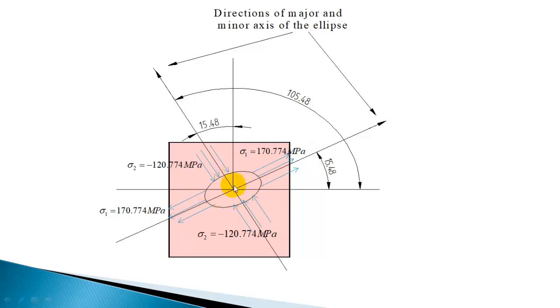So the major axis will be in this direction because as a result of this pull, the diameter will increase, and also this compressive stress is increasing the diameter in the perpendicular direction. And now in this direction the diameter will decrease because of the compressive stress, and also because of this tensile stress, which also decreases the diameter; lateral strain is induced here. So you have to find out the major axis and minor axis of the ellipse. You can find out the strain in the direction of the major principal stress.